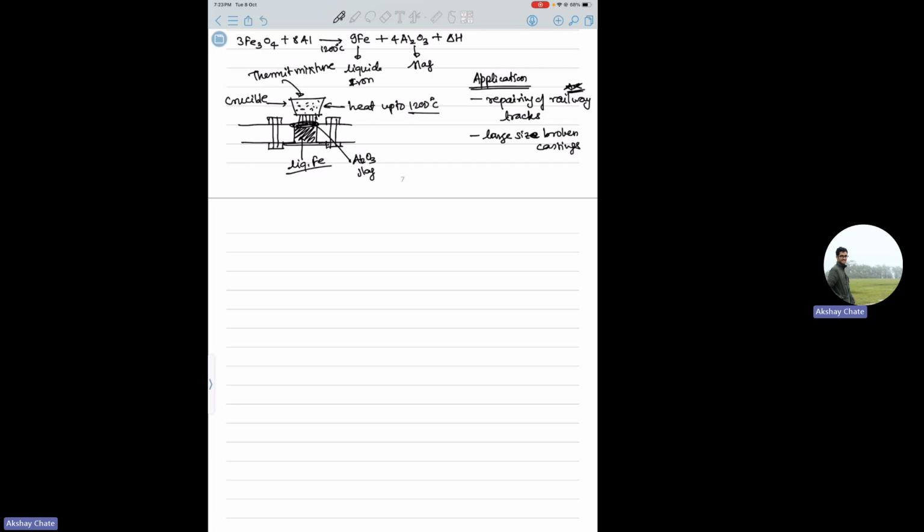As the name suggests, it is a projection. On one workpiece you'll have projections, and the other will not. Those projections act as initiation points of melting, because the resistances are higher there, and then you press or squeeze.